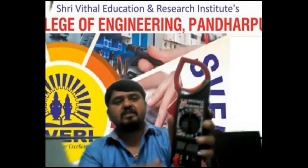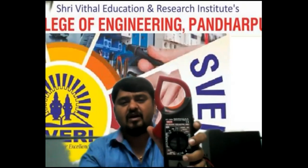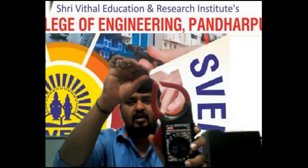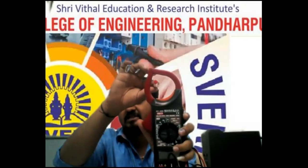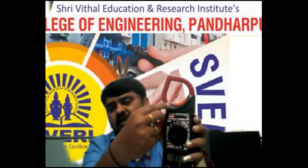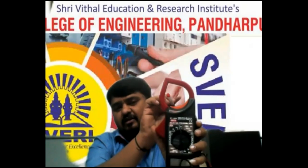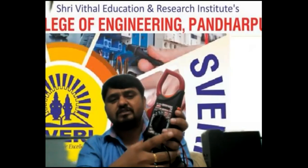Some maintenance persons came here for some work, so I have taken this from them. See here, they have provided a clamp like this. Whenever the conductor comes inside, we take it in. Because of this, the conductor acts as the primary winding, and inside it the secondary winding is there. We are going to measure the current here. This is bar type as well as toroidal type. We are going to use this.